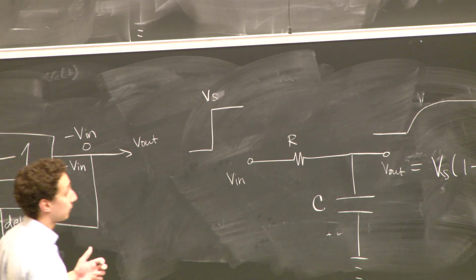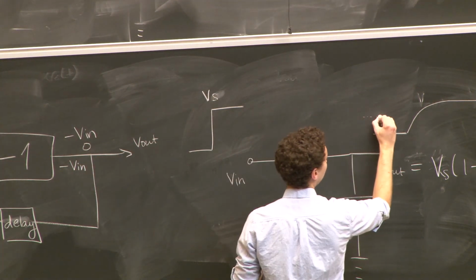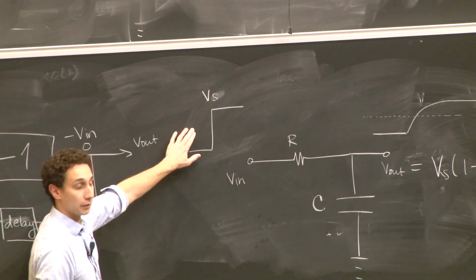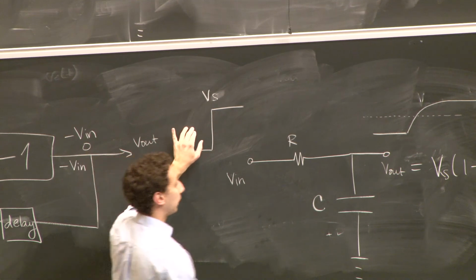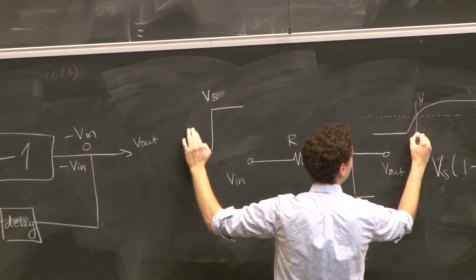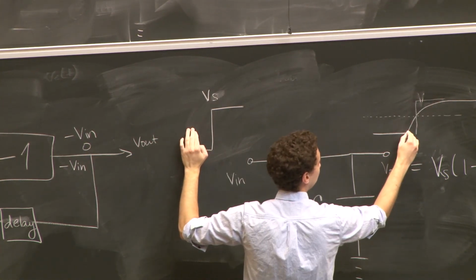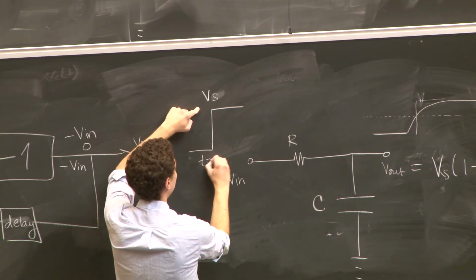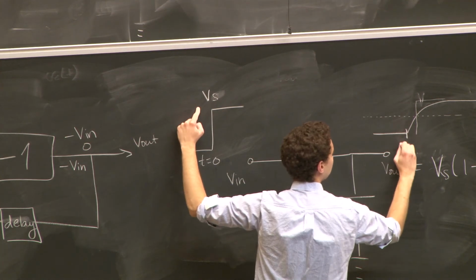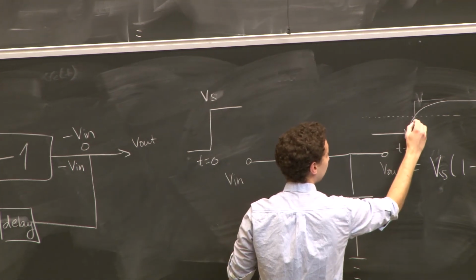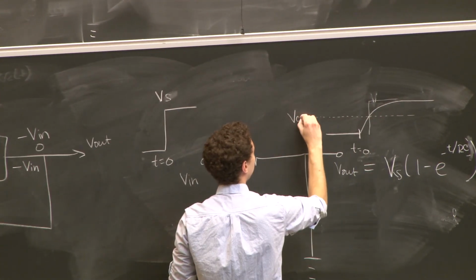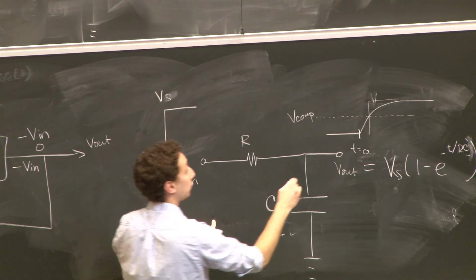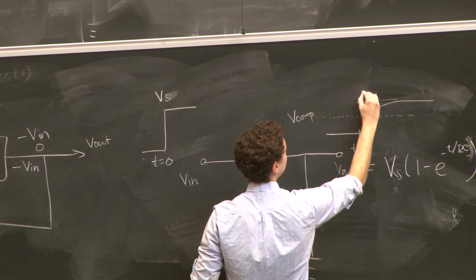And if we make it so that we have some comparator voltage in the middle here, sometime after this has occurred, we'll get a switch that looks like this. So the actual wave that came in, this switch, Vs, switched at some time t equals 0. Over here, here's t equals 0. And this, if I put my comparator, V comparator, there, will switch a little bit after. There's some time delay.